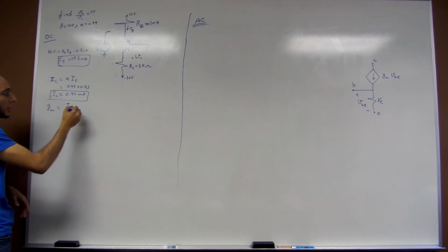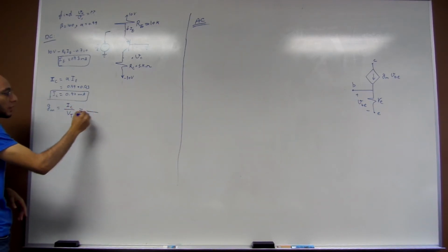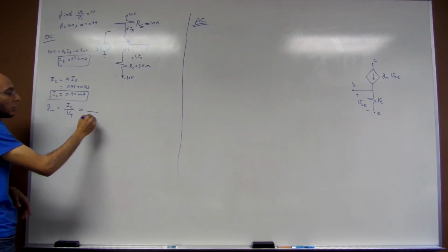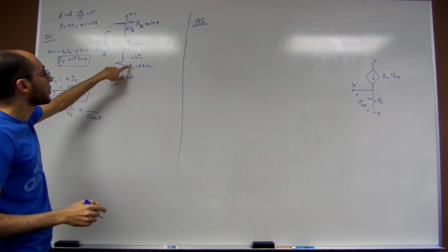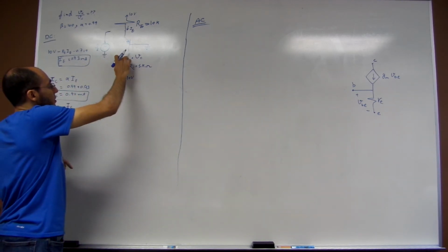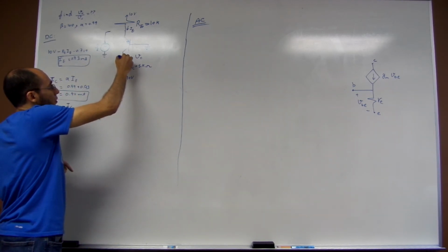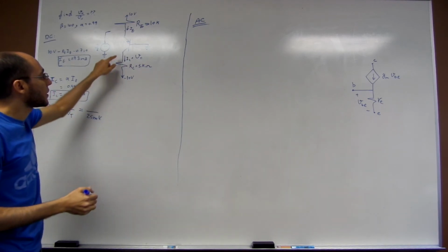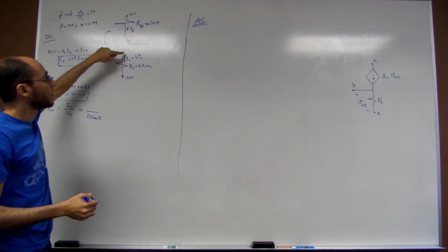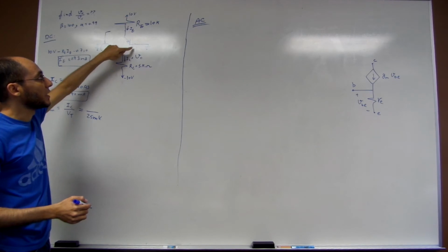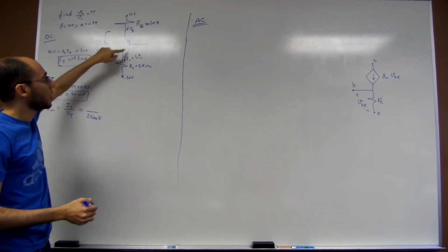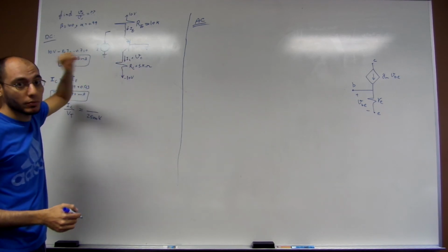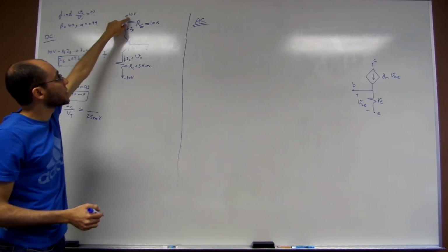So let's find the value of IC. How do we get the value of IC? Well, if you look, 25 millivolts, that is for the VT. If you want to get the value of IC, which is this current, you do not have the value of VCB. You do not have this value, and thus you cannot make use of this loop, right? So what we can make use of is this loop.